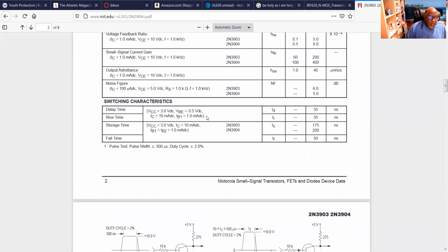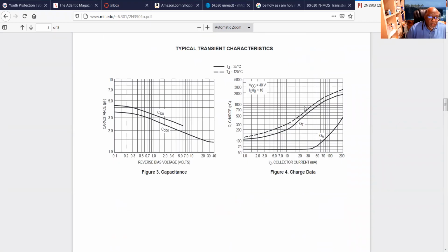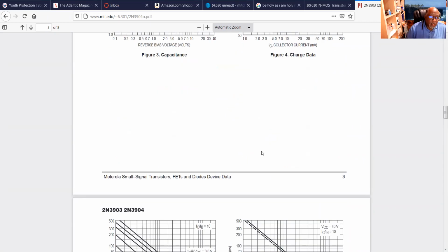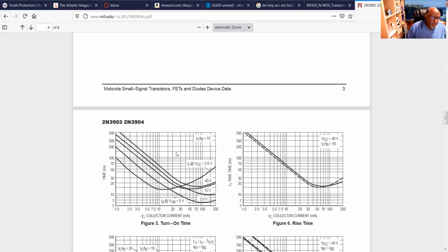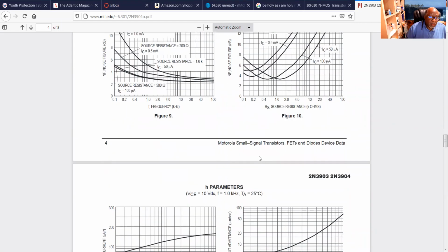And then you have switching parameters, for when you're using your transistor as a switch as opposed to an amplifier. Okay, let's see if there's something here I want to see quickly. This capacitance. Looking for your beta or your hFE as a function of current.